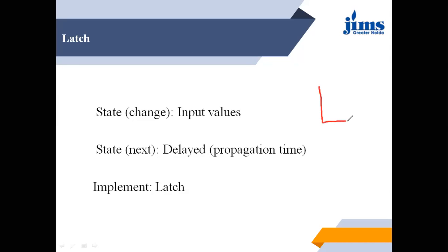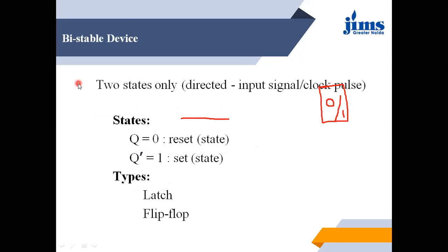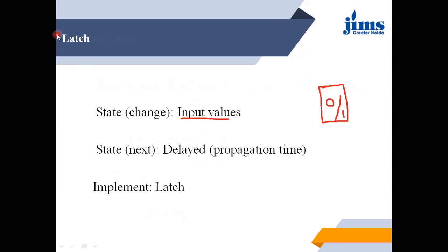Latch is a bistable device where we have either value 0 or 1, and the value is going to change based on the input value, as we discussed before, that the two values are going to change based on the input signal and clock pulse. So when the value is changed by the input signal, that is called a latch.